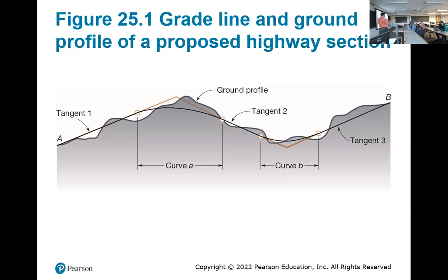Anybody drive down a highway that was cut into the side of a mountain? It's fairly obvious. The mountain side is a cut, and the other side is a fill, where there's a guide rail so you don't go off. They walk the road up the mountain gradually. That's where the finished grade profile, and doing a profile of your roadway alignment, is going to help.